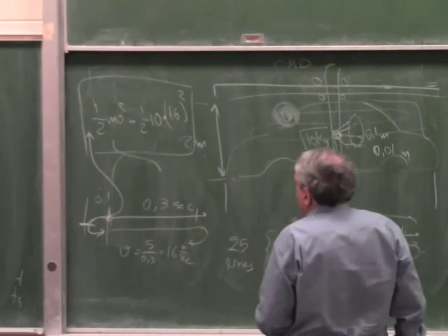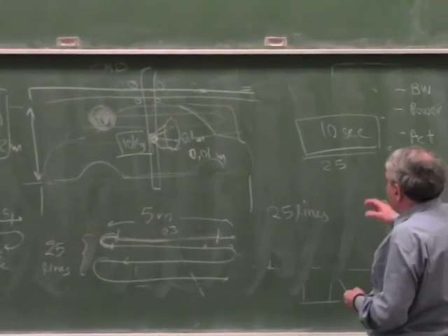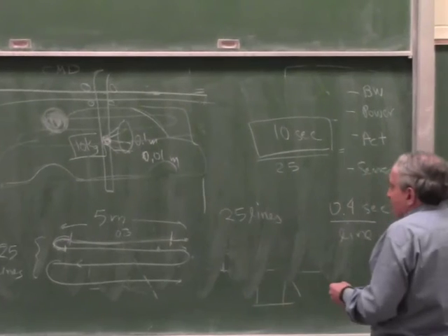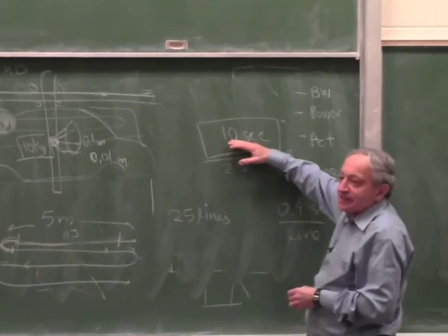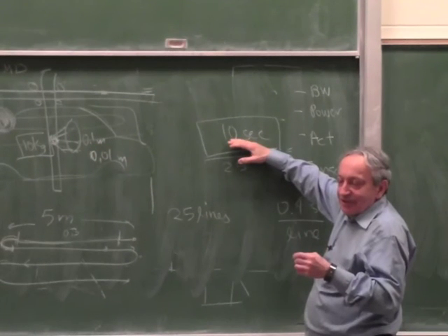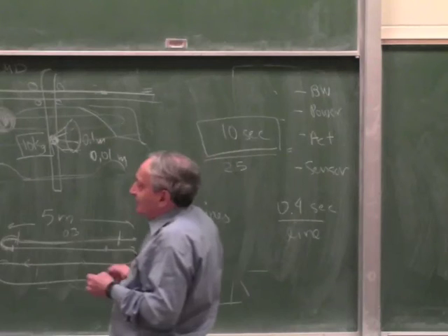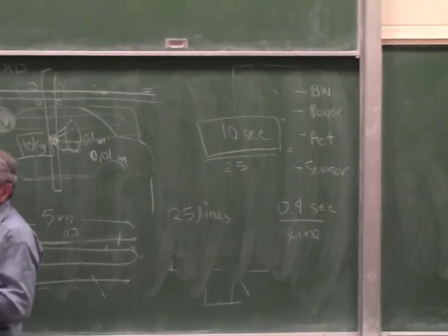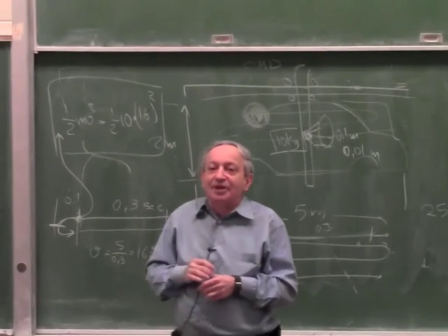Okay, so if you want to know the power, a line is 0.4 seconds, so 2.5 times a second, because you have 25 lines in 10 seconds. So 2.5 times a second, you have to decelerate and absorb 1300 joules, and then you have to accelerate and output 1300 joules, but we count it as the same.